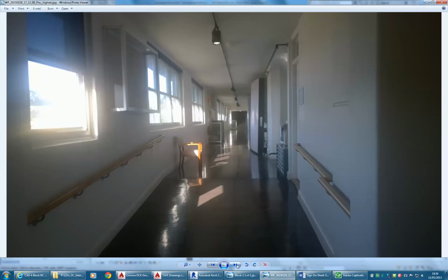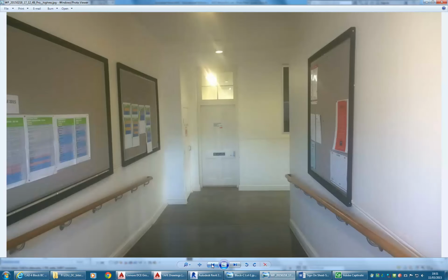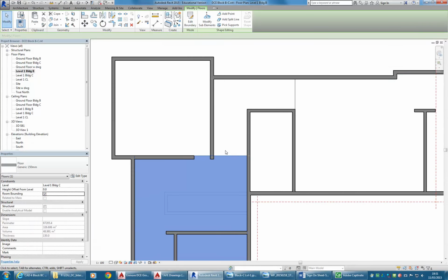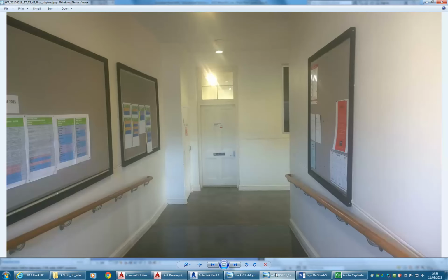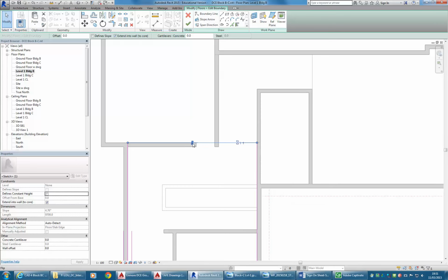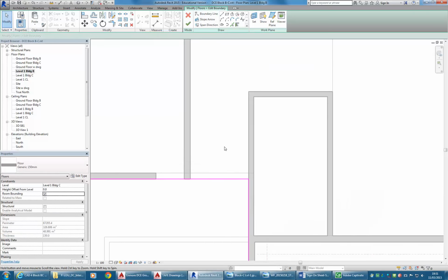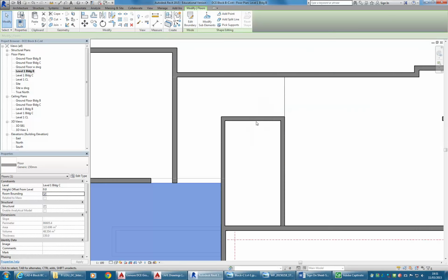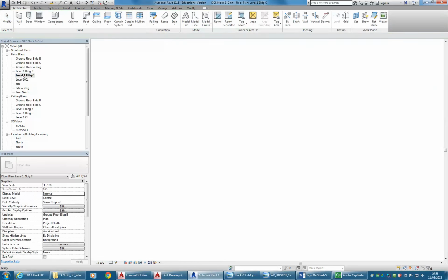And that's really the final thing I want to show you, just how to get started doing things like ramps, and stairs I might look at separately. So we've got there the floor level at the end of that corridor. Again here, I might just move this floor edge slightly because it finishes in line with the end of that wall. So again, edit boundary, I'm sure you're all used to that. Flipping the wall, and again here, when I flip it, not too bad. Even though these have been made with pick walls, it was made differently, so that's okay. And so then finally, tick finish, and I can go to the lower level, which is building C.